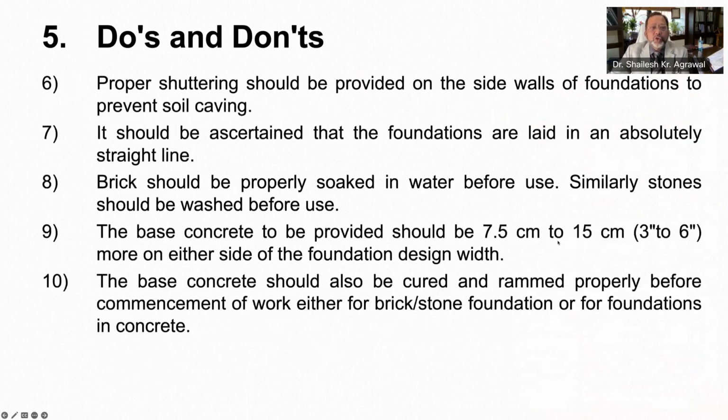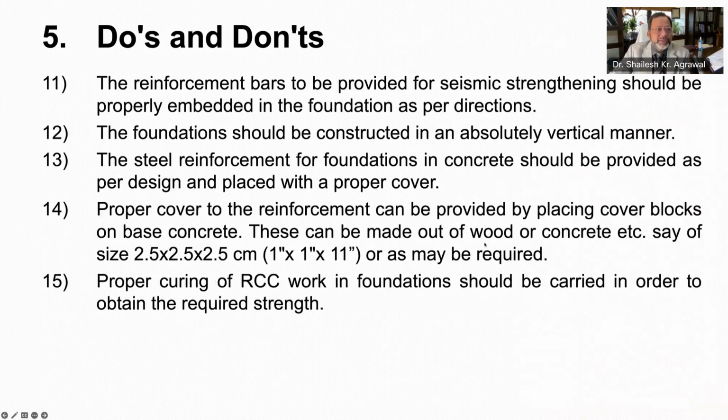Proper shuttering should be provided on sides of walls of foundation to prevent soil caving. It should be ascertained that foundations are laid in an absolutely straight line. Brick should be properly soaked in water before use. Similarly, stone should be washed before use. The base concrete to be provided should be 3 inch to 6 inch on either side of the foundation design width. The base concrete should also be cured and rammed properly before commencement of work, either for brick or stone foundation or for foundation in concrete.